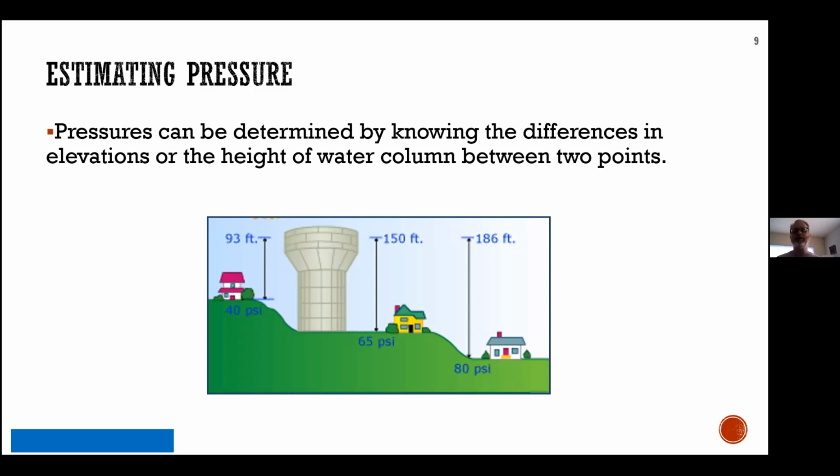And you can do that same estimate wherever you are in the system without seeing the tank or the pump, just by putting a gauge on a hydrant or on a tap at a place of business or a resident if they're complaining about low pressure. You don't have to tell them there's only 20 meters of head, but you will know that just simply by making the calculation off the gauge.